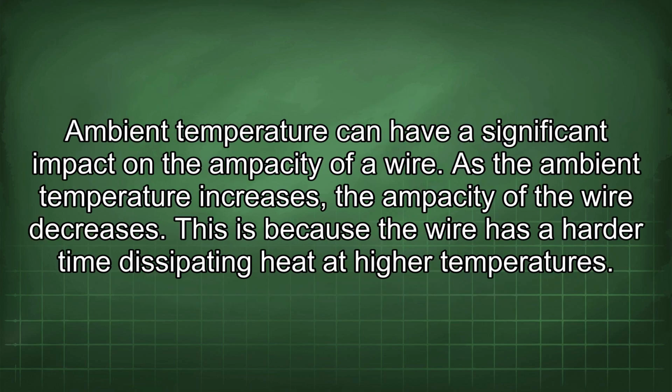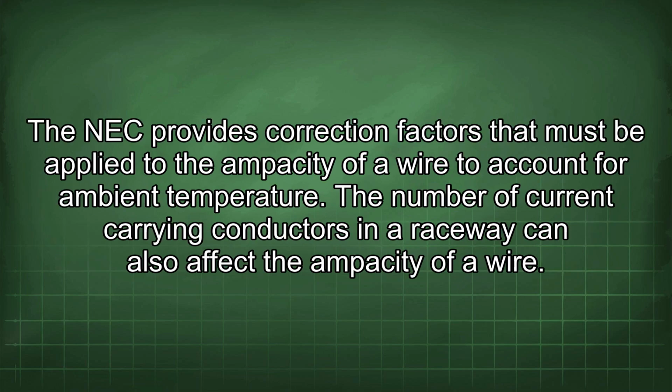Ambient temperature can have a significant impact on the ampacity of a wire. As the ambient temperature increases, the ampacity of the wire decreases. This is because the wire has a harder time dissipating heat at higher temperatures. The NEC provides correction factors that must be applied to the ampacity of a wire to account for ambient temperature.